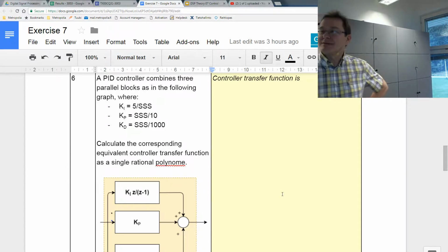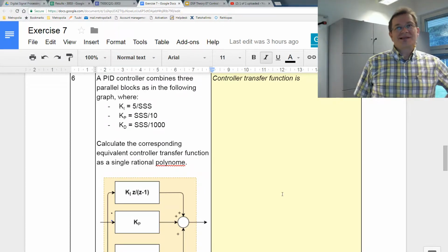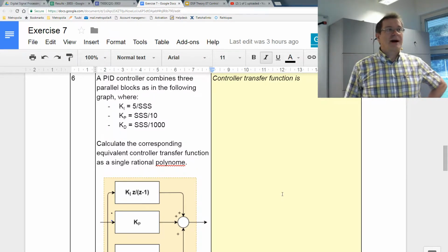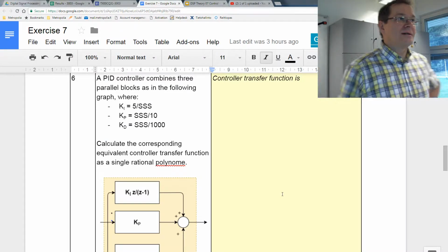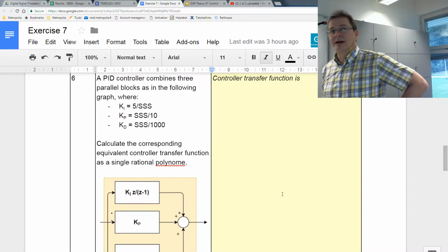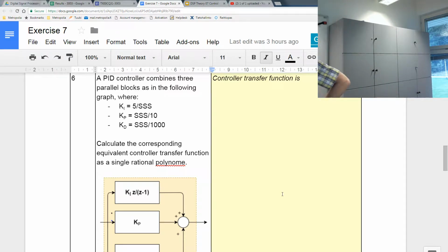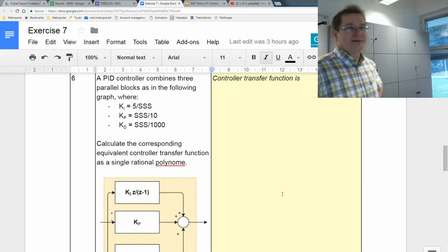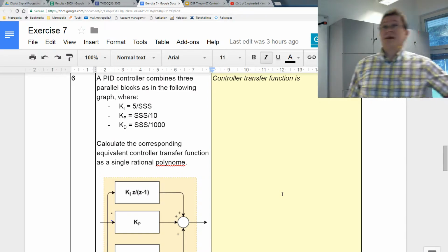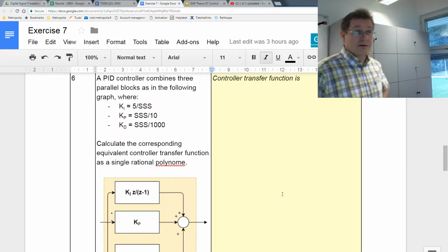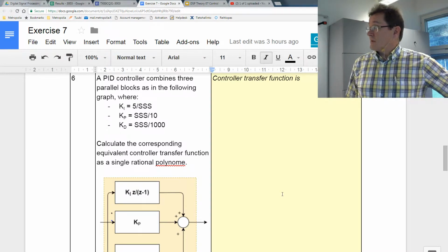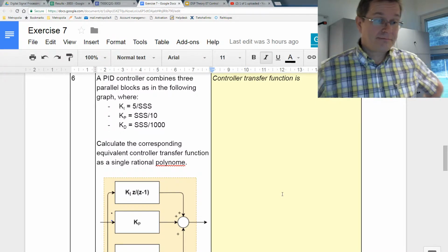With small numbers you would get quite long settling time and quite short rise time, and with the big numbers you would get, I think, an overdamped system, meaning long settling time, long rise time.